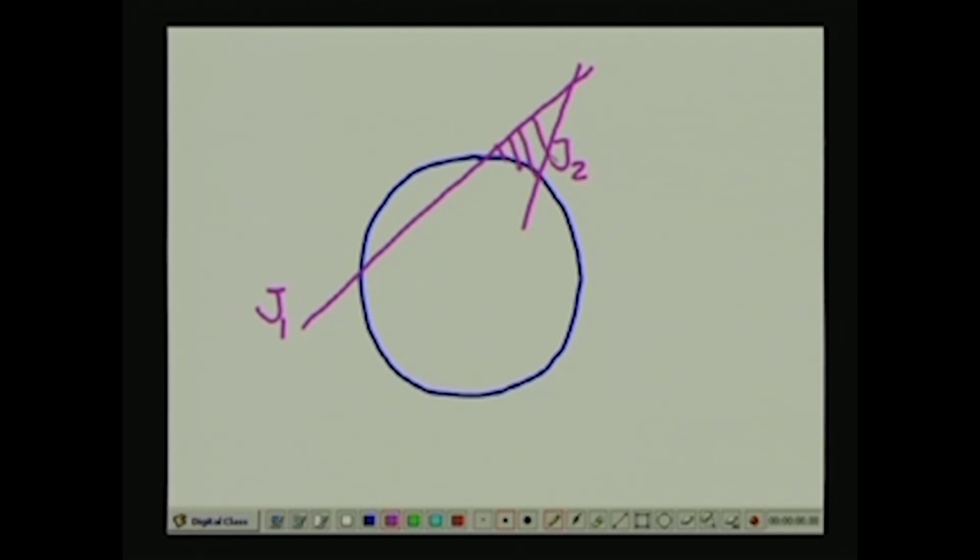Then you cannot always say whether this particular wedge is going to be susceptible to falling over into the tunnel opening, because of the frictional strength of the bottom surface of the joint and the dilatancy along the top surface of the joint.